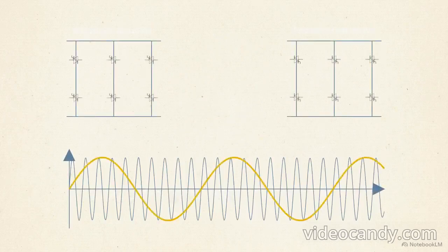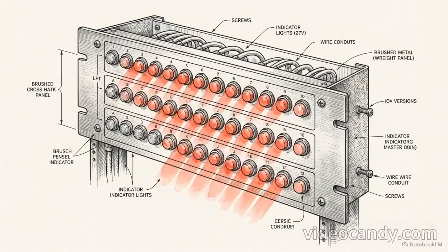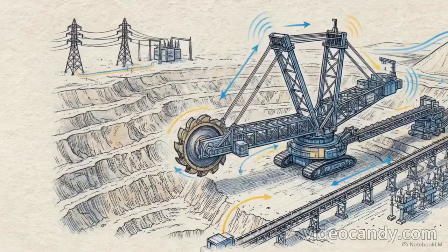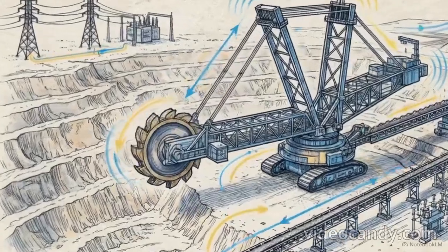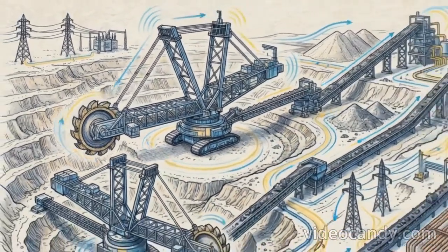Beyond motor drives, this exact same topological framework is used to precisely tune resonance in megawatt-scale industrial induction heating furnaces. The foundation lies in a simple anti-parallel SCR arrangement, acting as a static breaker. Scaled up, that simple breaker evolves into a dual bridge system capable of direct AC synthesis.